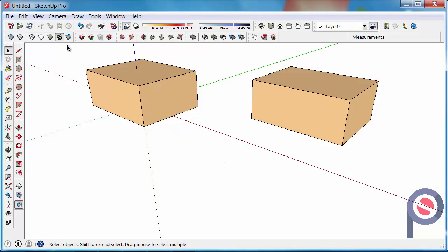If, for example, I have the object selected and I want to deselect certain elements, I could hold Shift on my keyboard, and you see how I've got the little plus and minus appearing on my cursor. I could hold Shift and then I could subtract surfaces and edges by clicking on them. And if I click again on those same surfaces and edges, it then adds them. So it's a plus and minus, meaning you can add and subtract from the selection. If I hold Shift and Control, you'll see that I get a minus. So whatever I click on will minus no matter what.